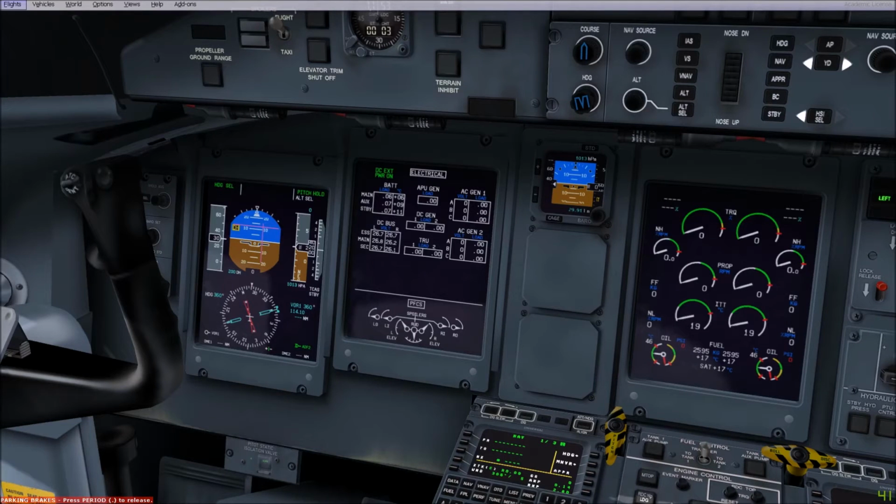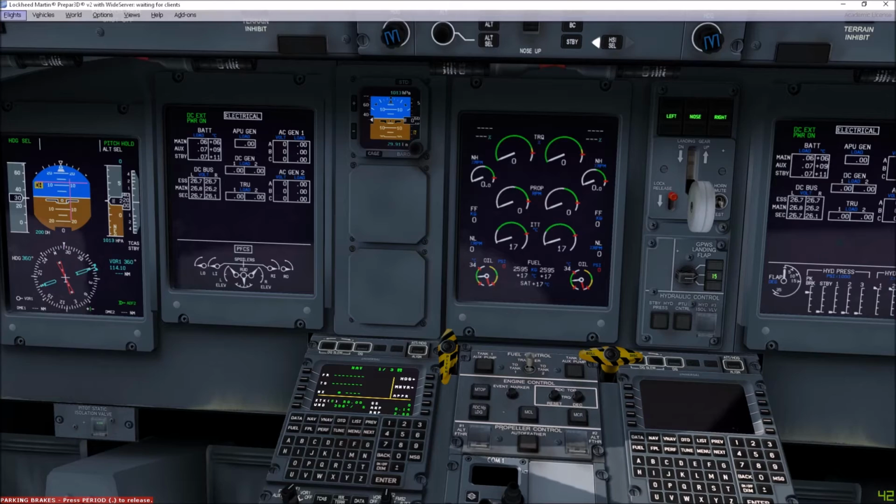The electrical system on the Q400 is fairly straightforward and also fairly standard. We have obviously both a DC and an AC electrical system. The AC system is generally only energised when the engines are online, though an AC external power source can be connected to the aircraft, though this is fairly rare. The external power indication is shown obviously by the green light at the top of the screen, DC external power on. And it's important to make sure that this light is illuminated if the APU isn't online. Otherwise, of course, electrical power will be draining the batteries.